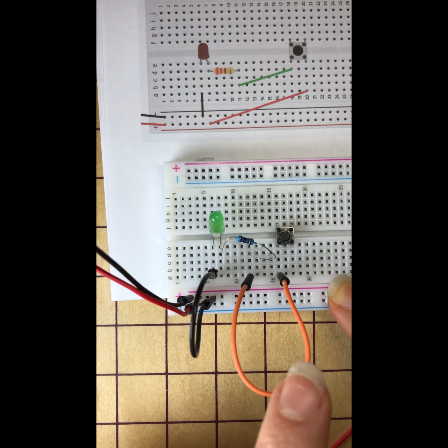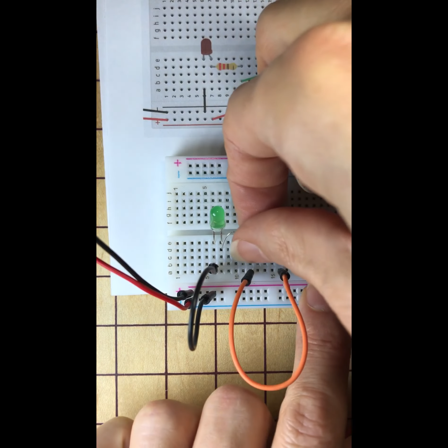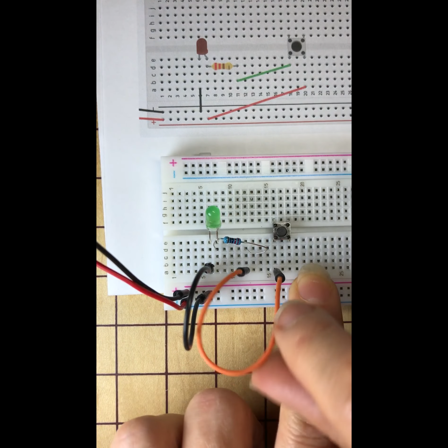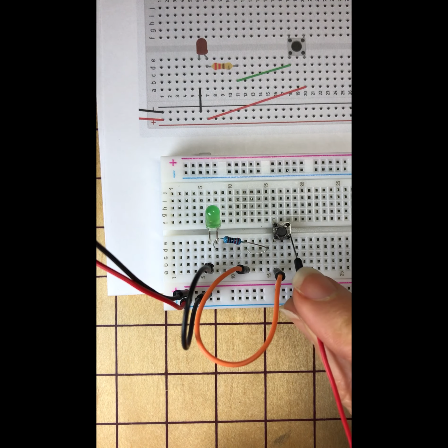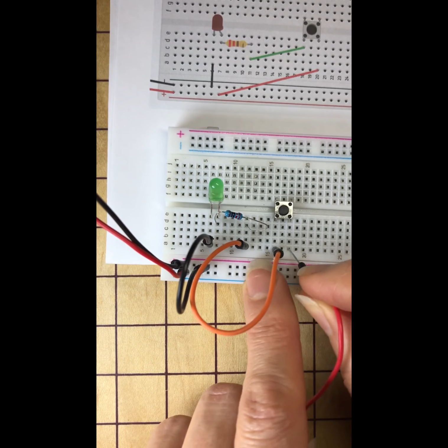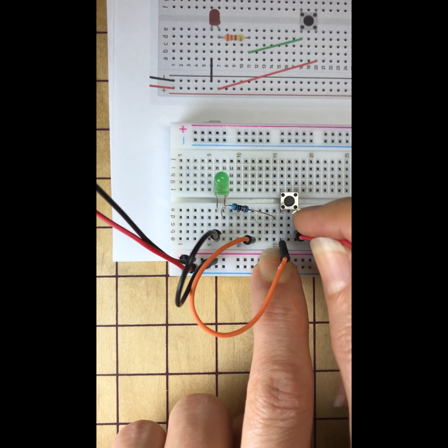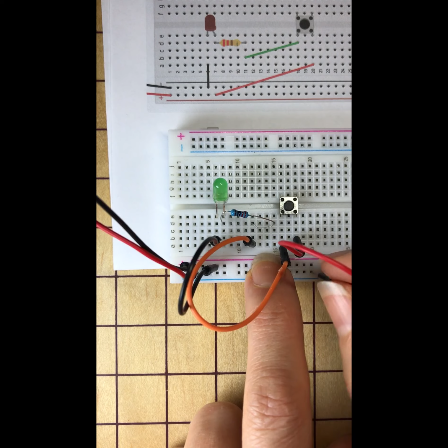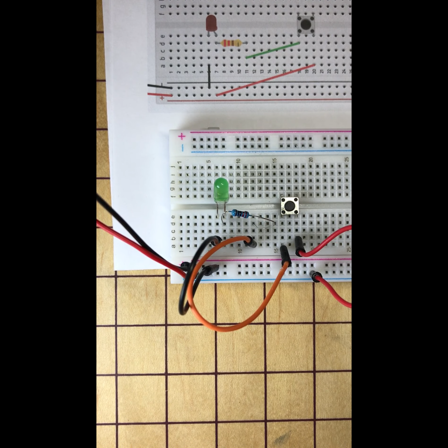The jumper cable is going from row 11 to row 18 on our diagram. As long as that jumper cable is in the same row as the resistor and the other end is in the same row as the button, then we are moving our circuit along. The last thing we're going to do is go from this last row of the button and make a connection in any of those ones there. So I'm going to move on because that one is not wanting to go. And then back to the positive power.